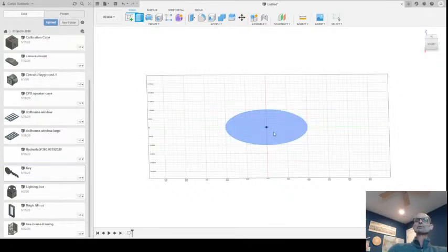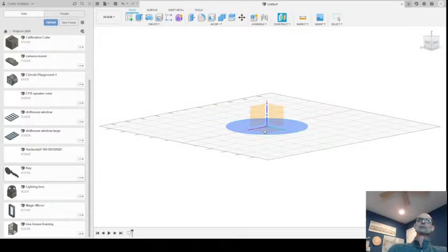And to do that, I would create a new plane that I could sketch upon, because we're sketching upon the XY plane right now, but I would need a new plane that's not the XY plane. So this would be where we would use a construction object. If I click on the construct menu up on the top toolbar, we're going to create an offset plane. So it's a construction object, and it can be offset off the plane itself down here, or the circle that's sitting upon that plane.